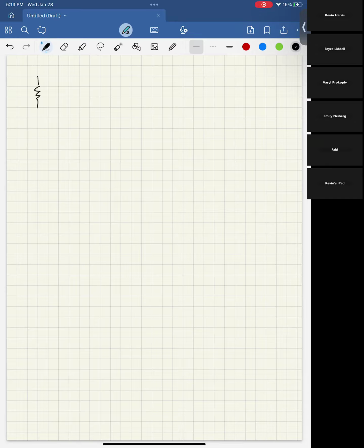If I have some kind of circuit where I all of a sudden have a split and there are two resistors that are next to each other, then I can approximate this as one resistor by a formula. There's a couple of formulas for it. The most general formula is 1 over R1 plus 1 over R2, which gives your equivalent resistance, right? And this continues to work for R3 and so on.